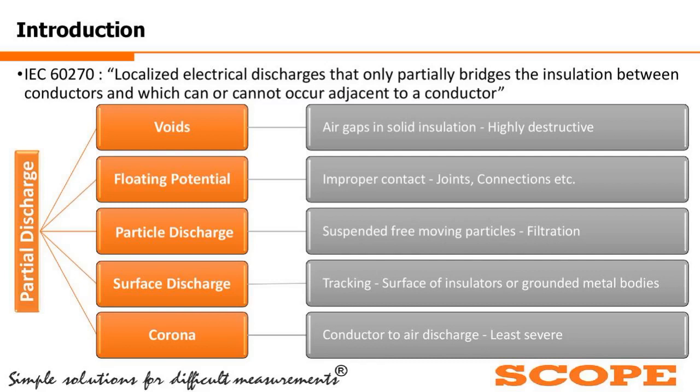Similarly, inside the transformer, there are so many other foreign objects other than the oil, like the spacers, the insulation tapes, there could be rusting inside the transformer body, or inside the OLTC there could be some sludge getting generated.